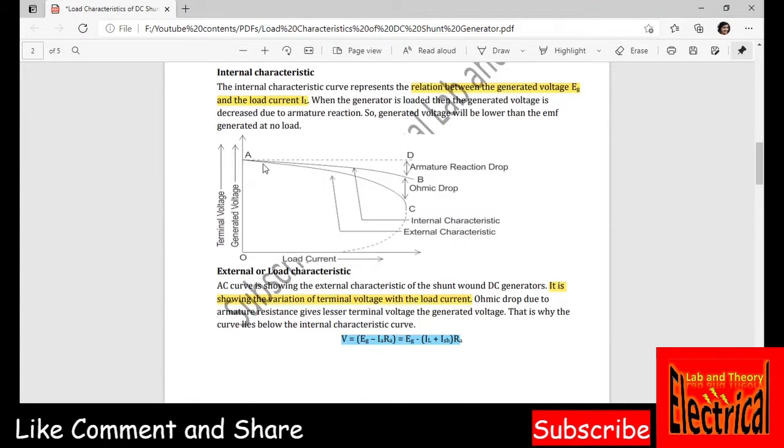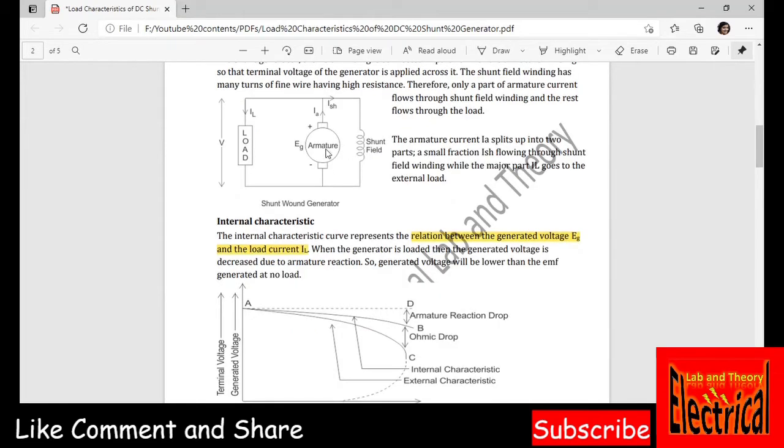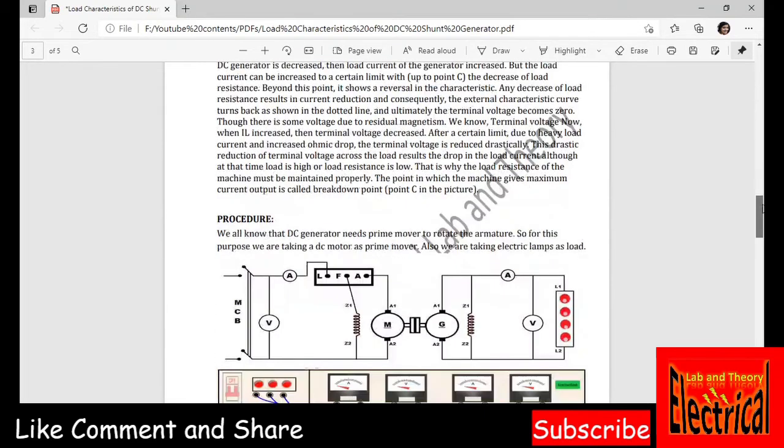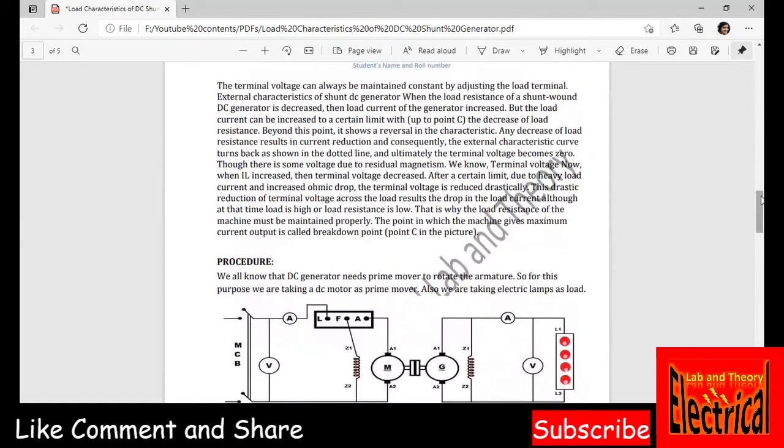Okay. External characteristics drop more sharply. So it has a drop because of ohmic drop. Ohmic drop means the I squared R drop, right? So that drop is incorporated here. And for this drop, the external characteristics are more drooping than the internal characteristics. Okay. So the same thing is written here.